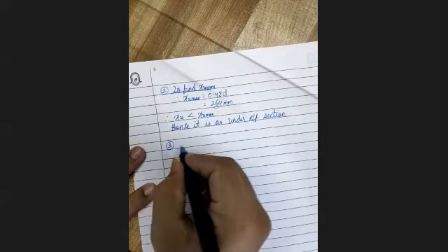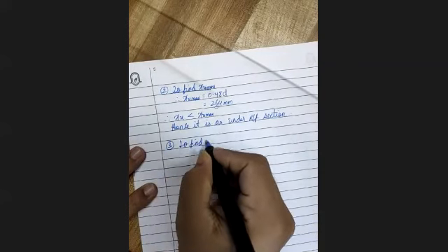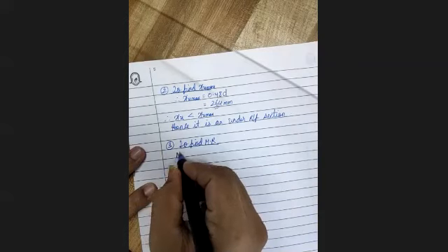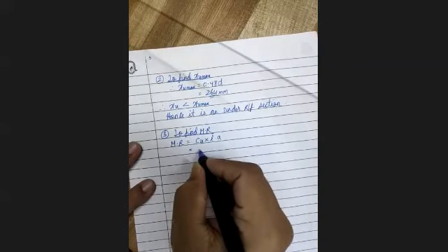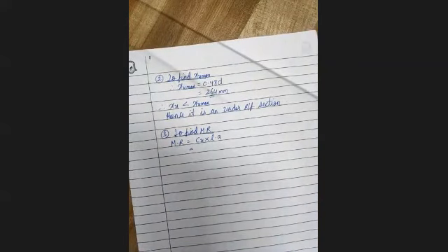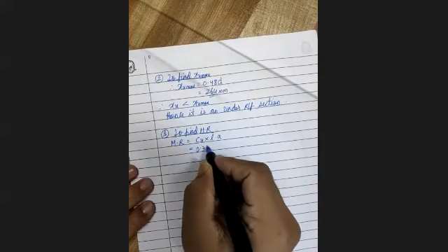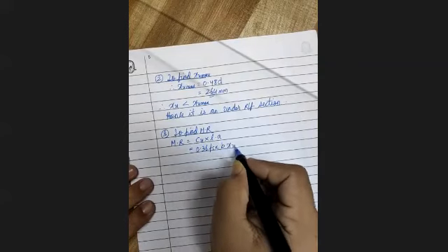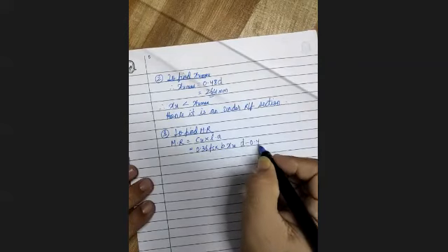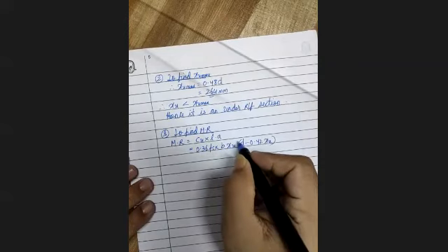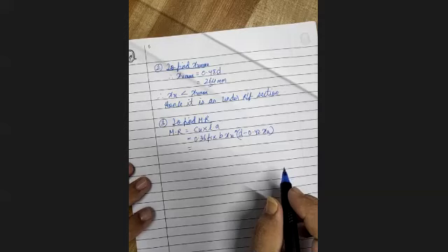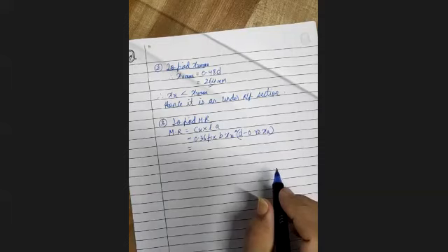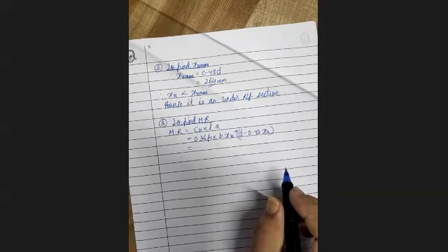Okay, so now we will find out MR. So MR is given by either CU into lever arm or T into lever arm. So give me the value of MR again. 0.36 FCK B into XU into D minus 0.42 XU. Yes, give me the value of moment of resistance. 263.11 is what I'm getting. Anyone else? Just confirm me the value.